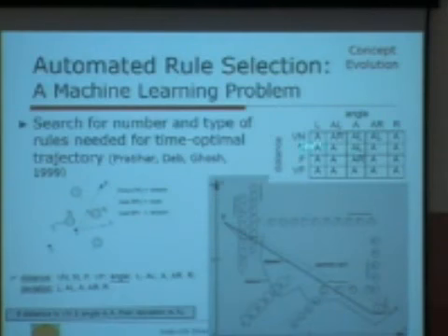That's where you use a set of fuzzy rules. We are not giving it the solution, but we are saying what kind of rules it should use, and we don't care about the exact angle or exact distance of the obstacle from the robot. So we use a fuzzy idea. For example, one of the rules could be: if the distance is very near and the angle is ahead, then the deviation of the robot should be ahead left, or things like that.